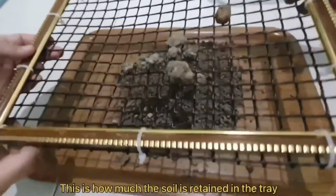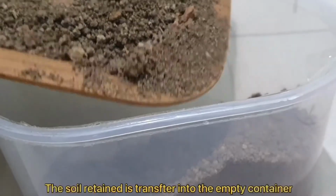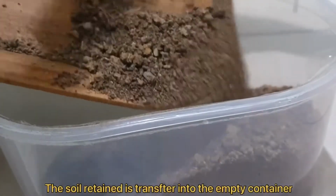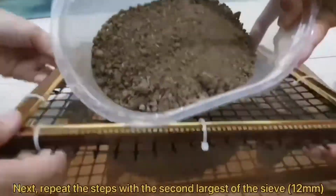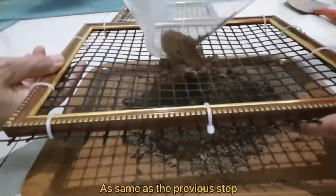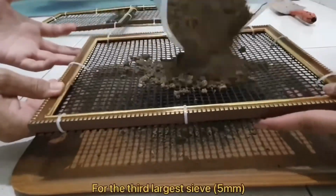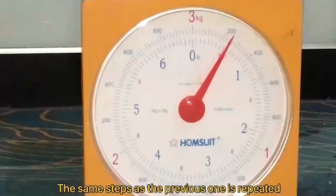As a result, this is how much soil is retained in the tray. By using a brush, the retained soil is transferred to the empty container, and then the mass of the retained soil is weighed and recorded. Next, repeat the steps with the second largest sieve. As with the previous step, for the third largest sieve, the same steps are repeated.